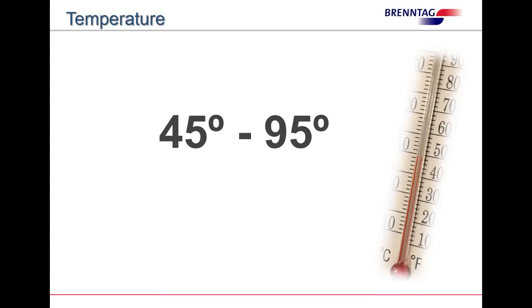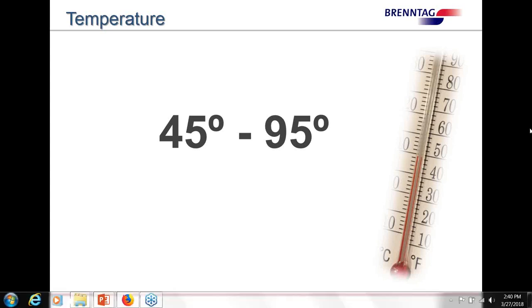Now, 95 is the textbook value. You can go up to about 102 to 103, and that's when you start running into nitrification problems. So you're going to lose your ammonia nitrification many times, especially at 104 to 105. You're really going to start causing them issues.